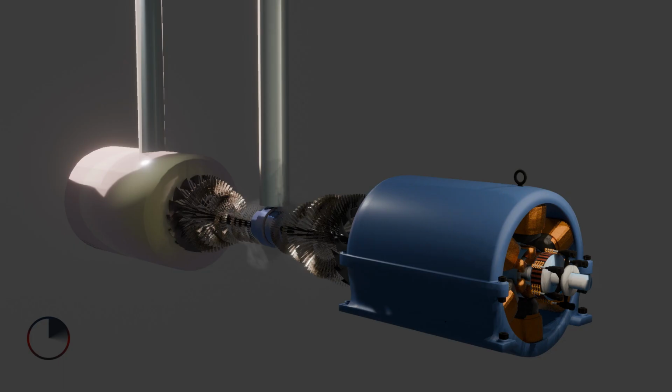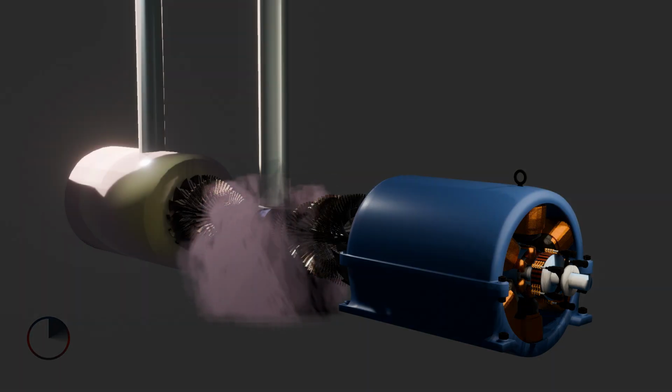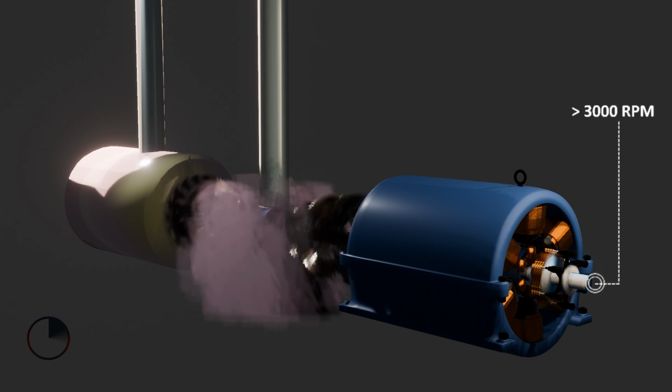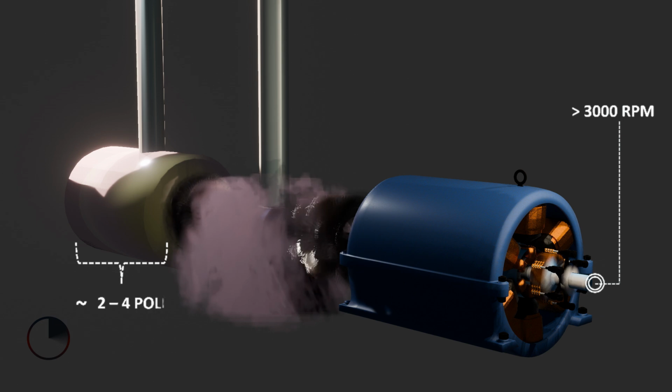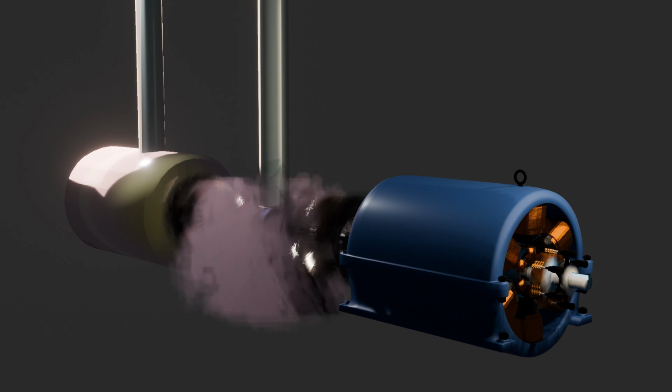In power stations that are driven by steam turbines or gas turbines, the power station usually uses an impulse reaction type turbine to convert fluid flow to mechanical energy. This power station operates at a higher speed of between 3000 to 3600 revolutions per minute. Hence, the structure of the generator is a non-salient type which usually has 2 or 4 pole field windings.